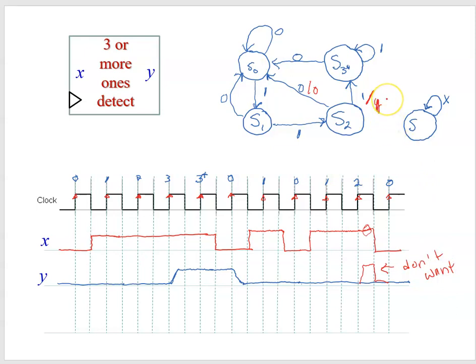we want our y to transition just, cross that out, we want it to transition just based on the state. So when we're in state 0, we'll have our output y be a 0, 0, 0. And up here, only when we're in state 3 will our output be a 1. And that looks like it'll satisfy our design criteria. We'd need to additionally, eventually set up timing criteria for setup and hold times.